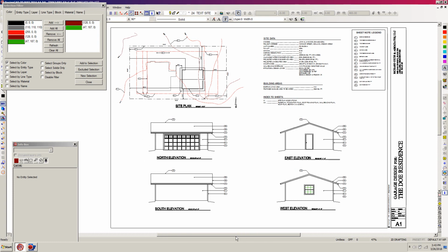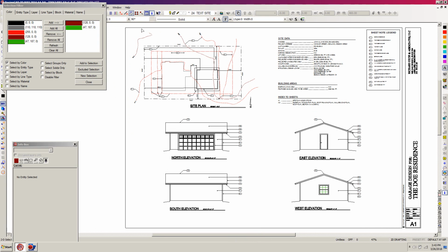I'm going to use my scroll bar over here to scroll a little bit over. What that means is, for these colors on this right hand side, when I do a selection rectangle, those are the only colors that will be selected. So I'm going to start my selection rectangle over here off to the left and up at the top, and just select the whole enchilada pretty much. But you can see that only the maroon topographic lines and the green window grids have been selected. So I'm going to turn those black.